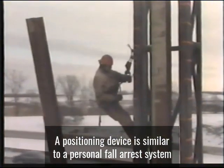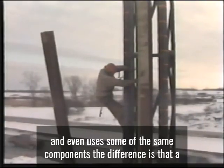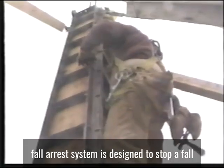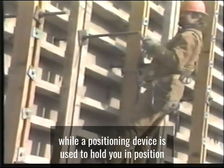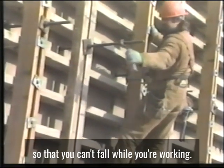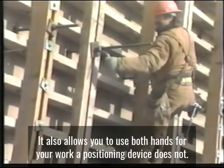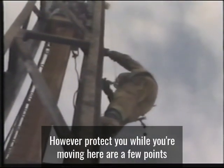A positioning device is similar to a personal fall arrest system and even uses some of the same components. The difference is that a fall arrest system is designed to stop a fall, while a positioning device is used to hold you in position so that you can't fall while you're working. It also allows you to use both hands for your work. A positioning device does not, however, protect you while you're moving.